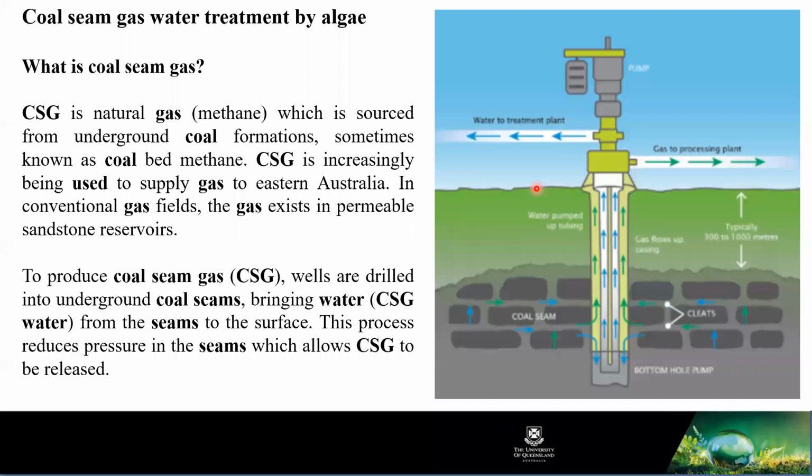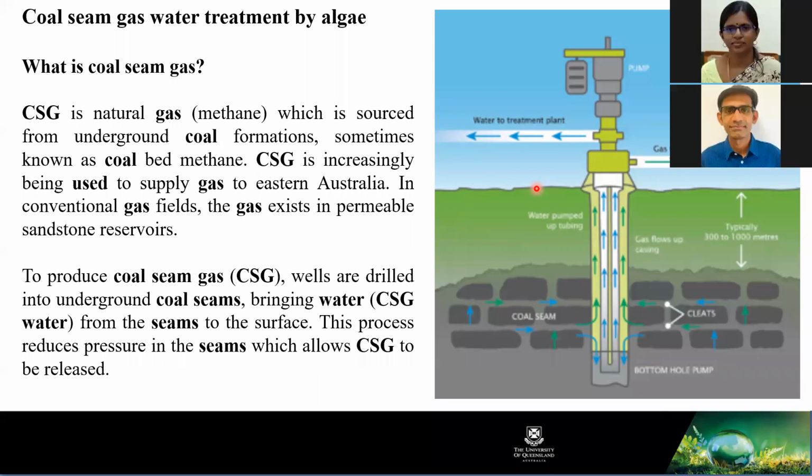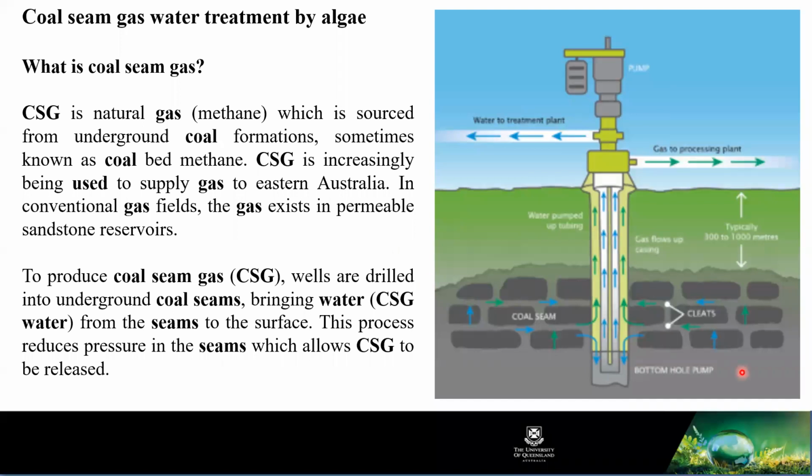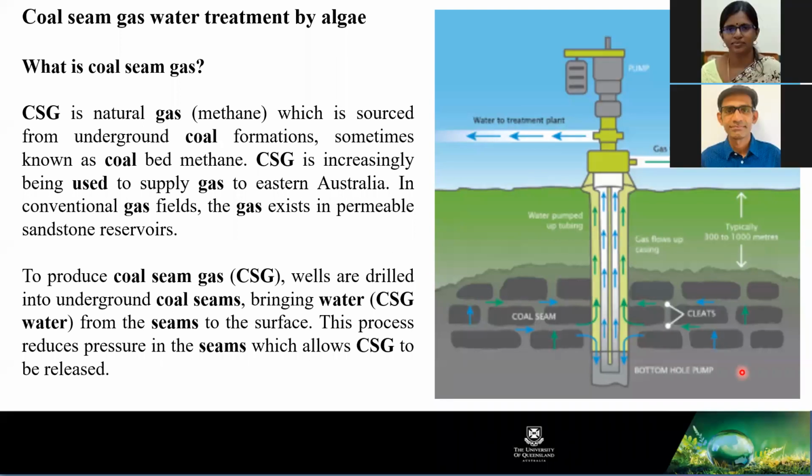Number one has a salinity of 25 parts per thousand. Okay. Number two, 320 parts per thousand, nearly that range. So they said, we want to get rid of this 25. Also, we want to get rid of this 300 plus. So when we were doing the research, we found out two algae are suitable for that. Number one is Spirulina, which is able to handle lower salinity. Number two is Dunaliella, which can handle high salinity.